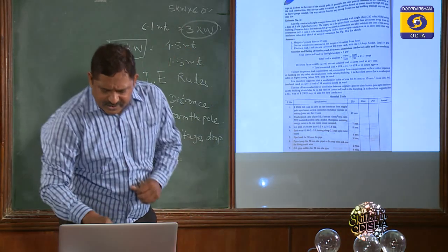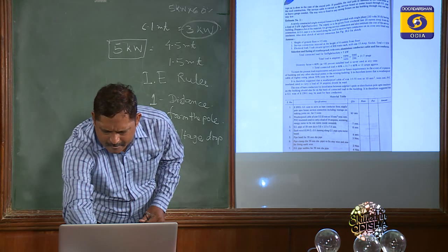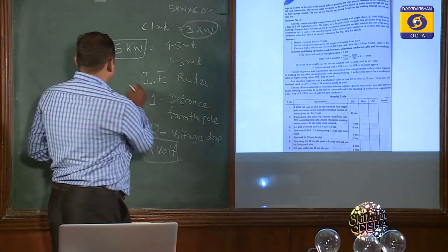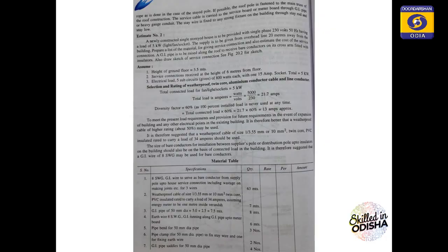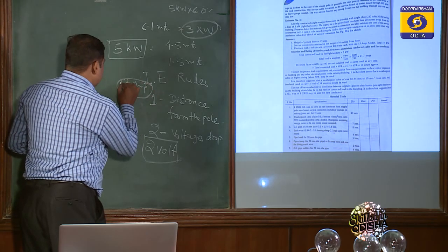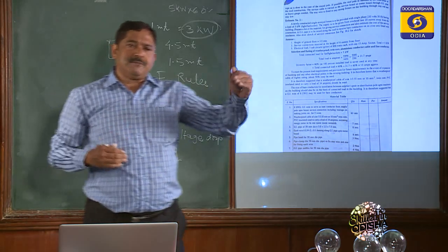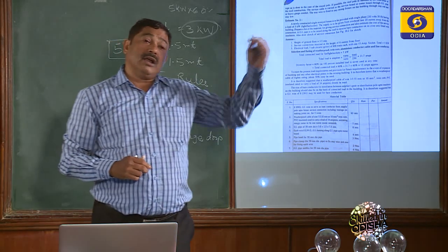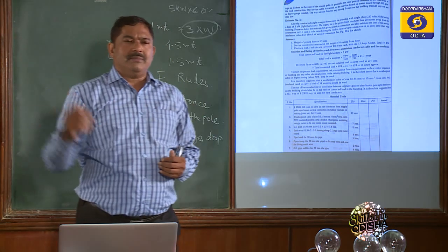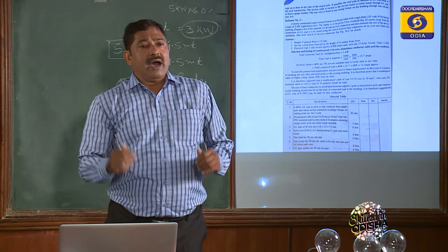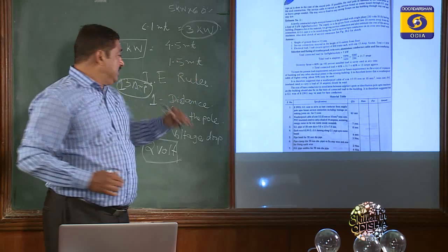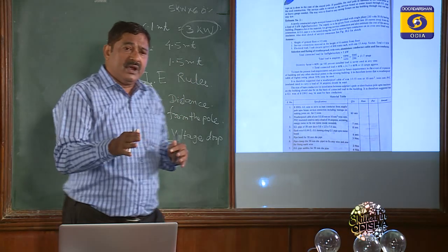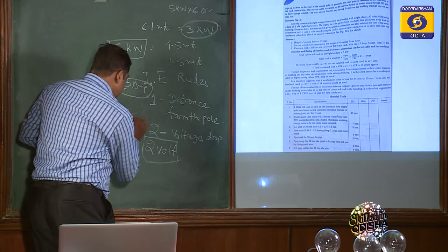If you calculate as per 3 kilowatt, it comes to around 13 ampere. You see, diversity factor 60%, it comes to 13 ampere. Again, for future expansion, we keep another 50% or 100% extra. Suppose somebody will come someday and add another AC, so another 10 ampere will increase. So we always think of future, and with 13 ampere we add another 50%. So it comes to say 20 ampere.